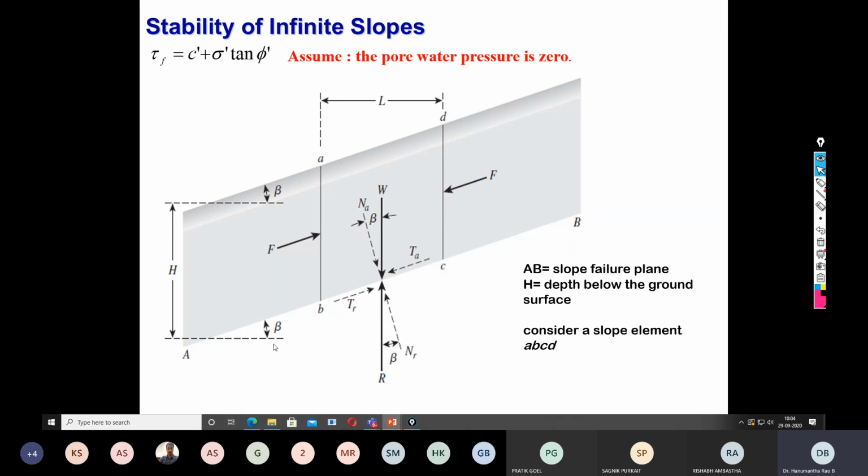Now let us consider any infinite slope, where the length of the plane is very long, an indefinite length. However, we know the soil formation on that strata is very shallow, which is designated as H. So H is the thickness of the soft soil layer. Instead of soft soil, understand this as a loose soil, and below is the hard strata, that is a rock.